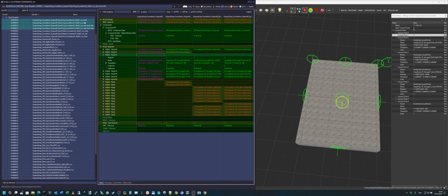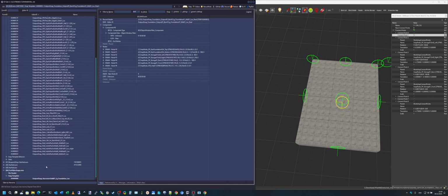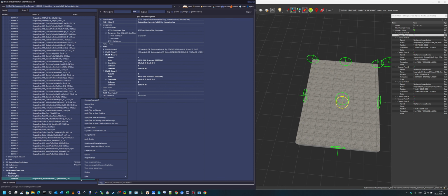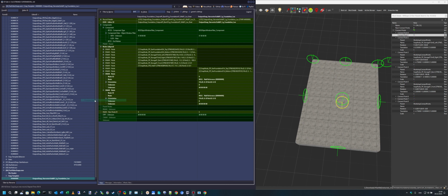For example, if you have large foundations and these are very similar, I can reuse some of the nodes. I can just press one node and drag it to the other. I won't do this here, but if you have a node in another file, you have to Ctrl multi-select, click. Now we have both lines selected. Right click on any of those and choose compare selected.